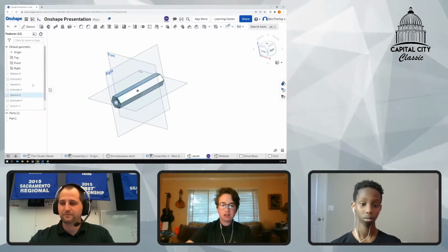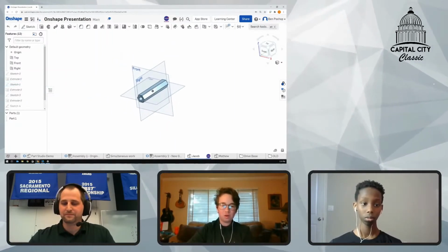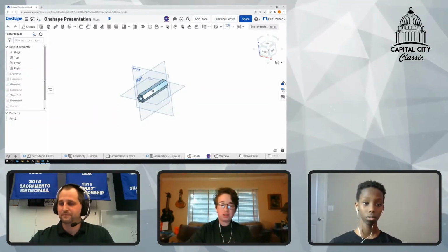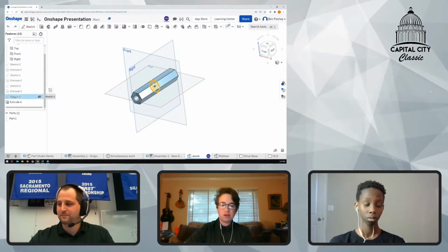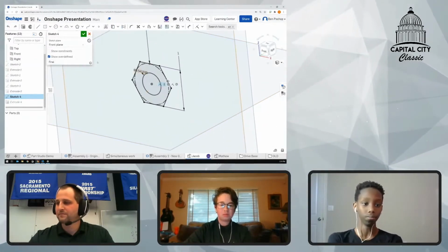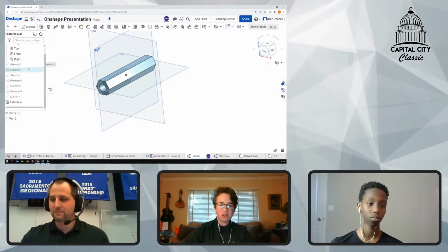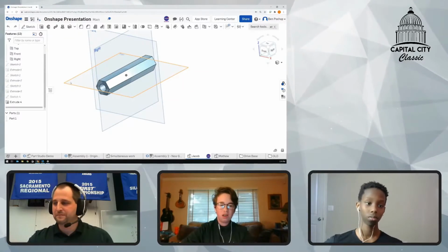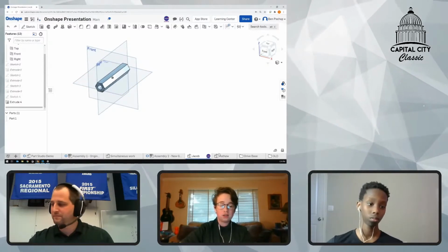So this shaft is 1 inch thick instead of ½ inch, which is what we normally use. That was because we told them to make a shaft that was ½ inch, and instead of dimensioning the opposite sides, they dimensioned it from the inside. The way we solved this issue is we used screen share and just showed them what the correct sketch should look like, and then they fixed it for themselves.